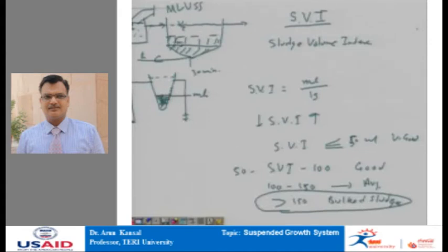So, to take so much kg of biomass into the system, we have to withdraw more volume. Similarly, this settled sludge has to go to the sludge stabilization unit like anaerobic digester, followed by sludge dewatering. So, more volume has to be given there. So, the requirement of volume of the anaerobic digester or sludge dewatering system gets increased, which results in poor efficiency for a given fixed pre-designed volume. So, bulk sludge is a problem, and it causes the problem because of this reason.